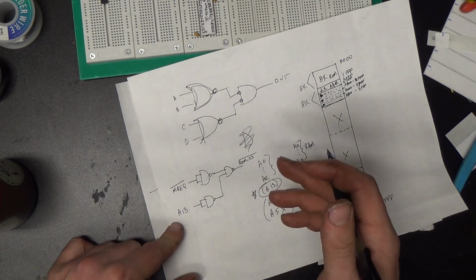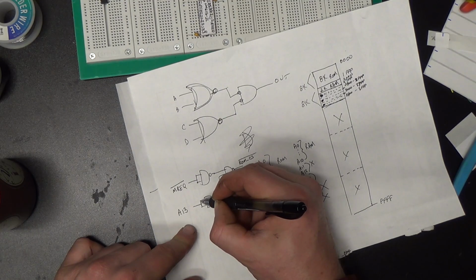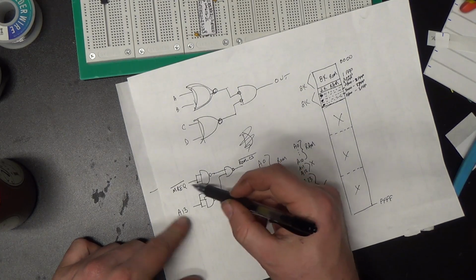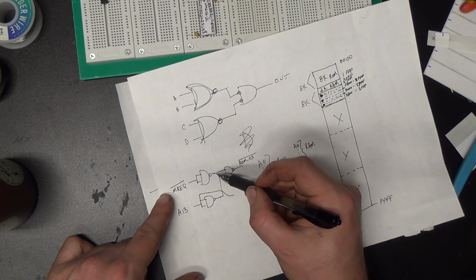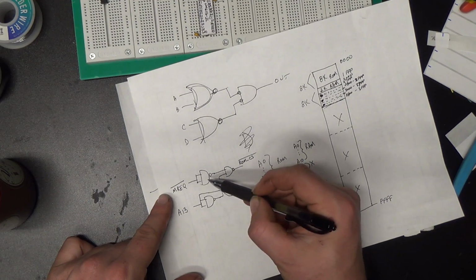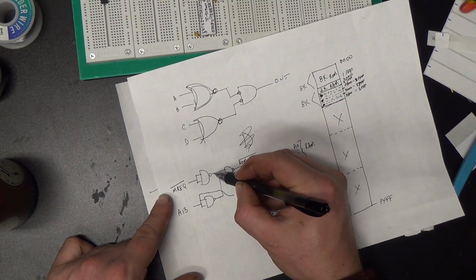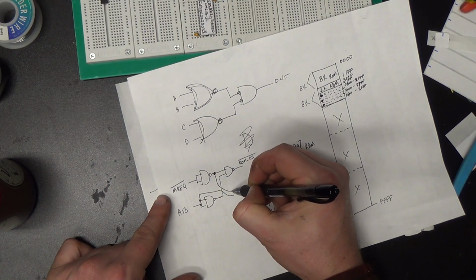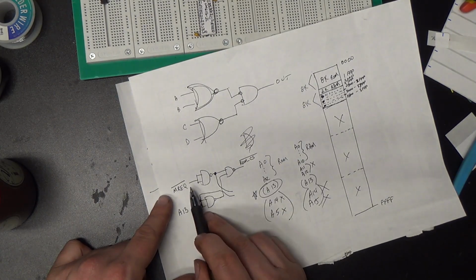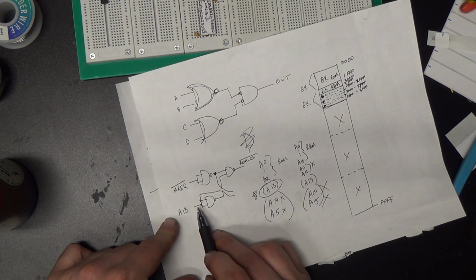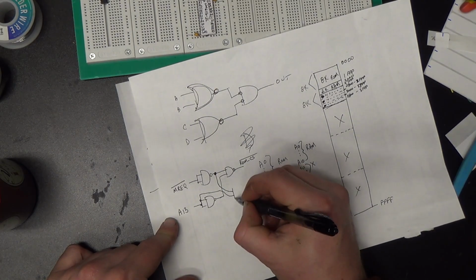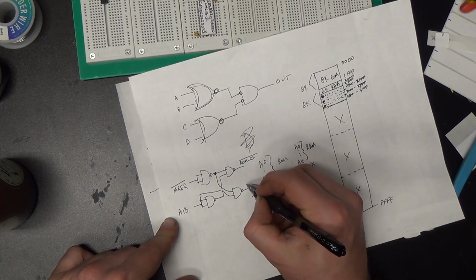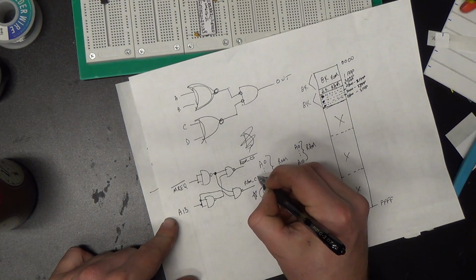Likewise, when A13 is high, we can pull it off of here and go up here somewhere like this, and when memory request is asserted, meaning it's low, and then it gets turned high by this inverter that we've made here, we can take the signal off of here. When both of these are true, when a memory request is in progress and A13 is high, then we want to have an active low RAM chip select.